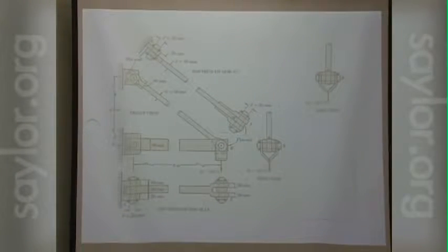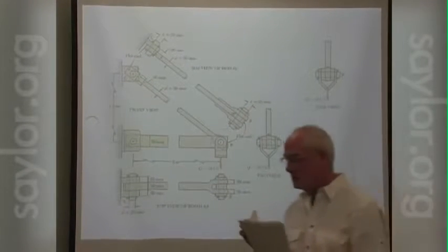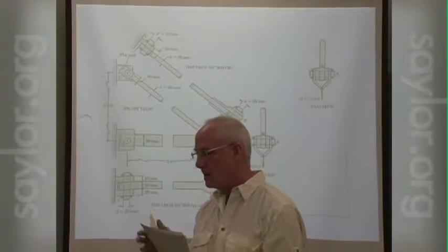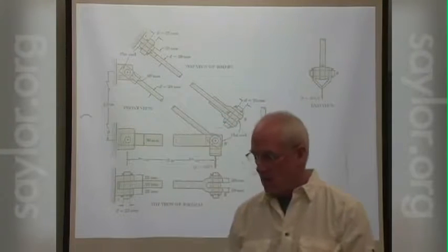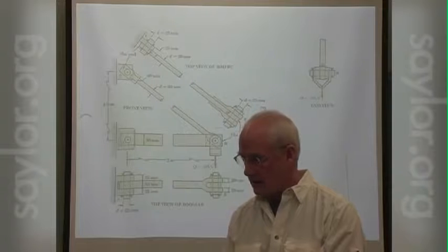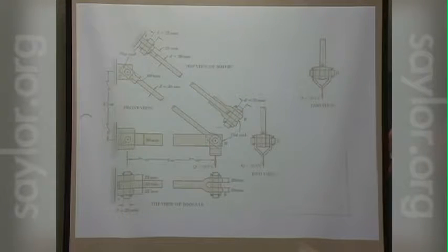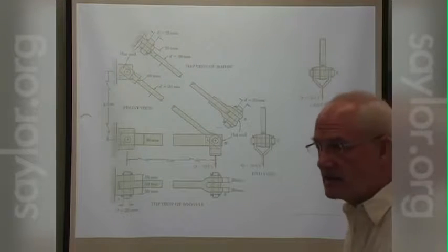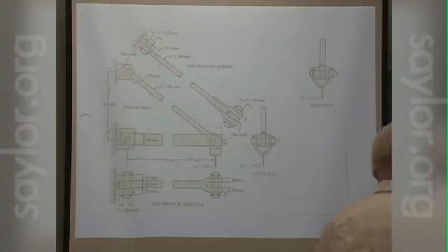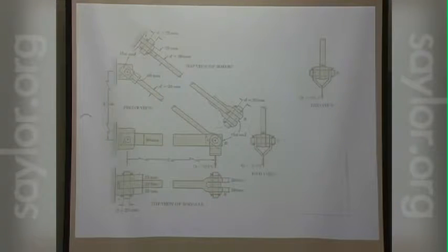But now we're going to look at the pieces themselves and figure out what some of the stresses are in those pieces, because, assuming that a piece is made out of the same material throughout, wherever the stress happens to be the greatest is going to be our place of greatest concern.